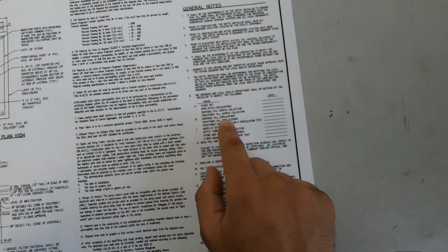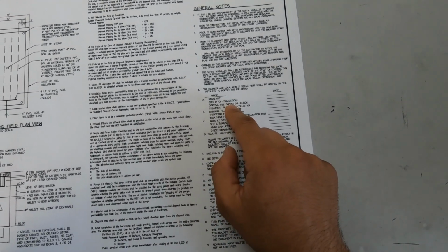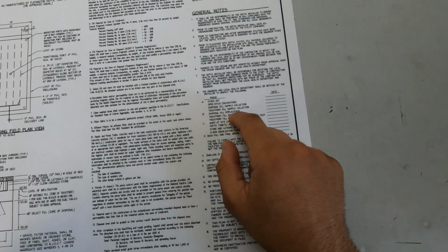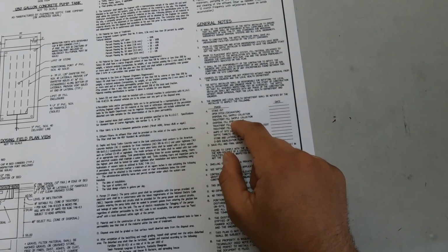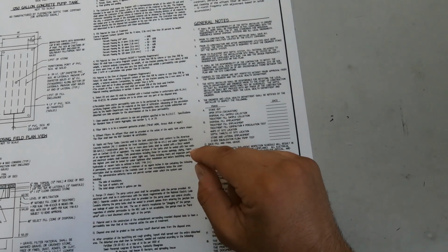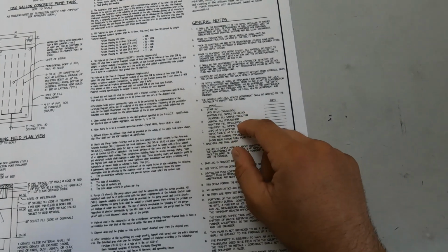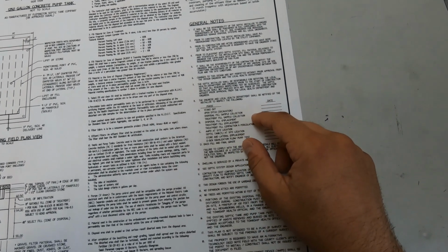For the sample collection, basically the contractor will have the sand delivered to the site. It usually takes obviously more than one dump truck, so this is usually an all-day affair or a half-day affair. But the trucks will drop off the sand. You'll visit the site at some point, grab a sample of the sand.